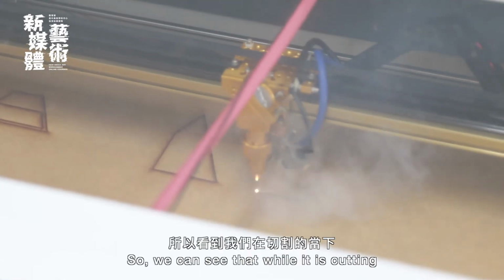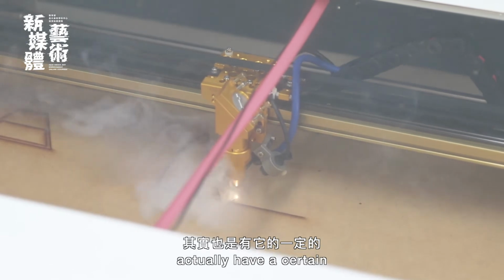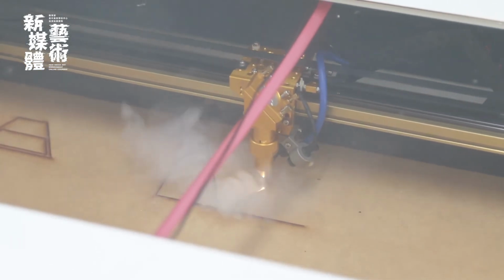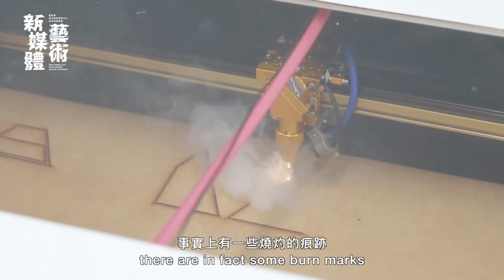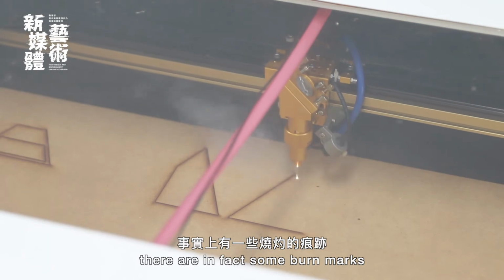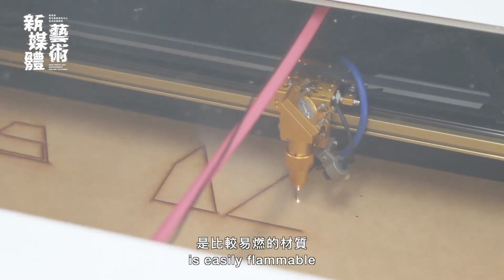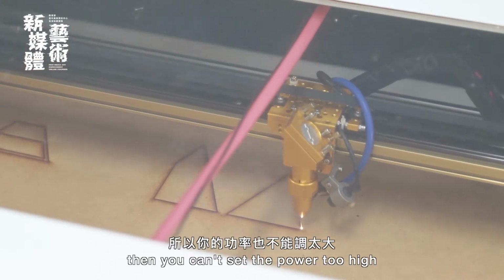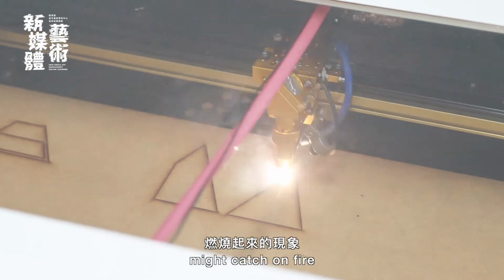So we can see that while it is cutting, the speed of its movements actually has a certain speed power setting. On our surface, there are in fact some burn marks. This time as well, if the material you're cutting is easily flammable, like paper, then you can't set the power too high. Otherwise, its surface might catch on fire.